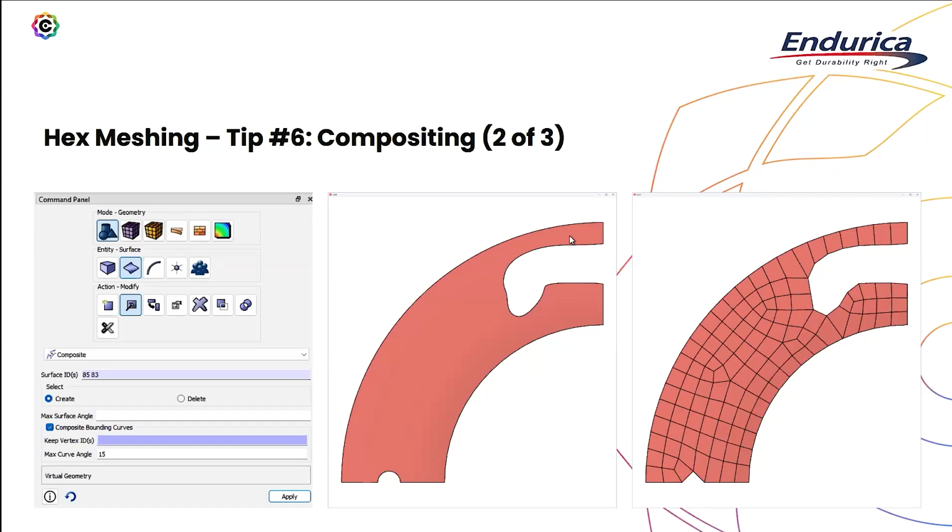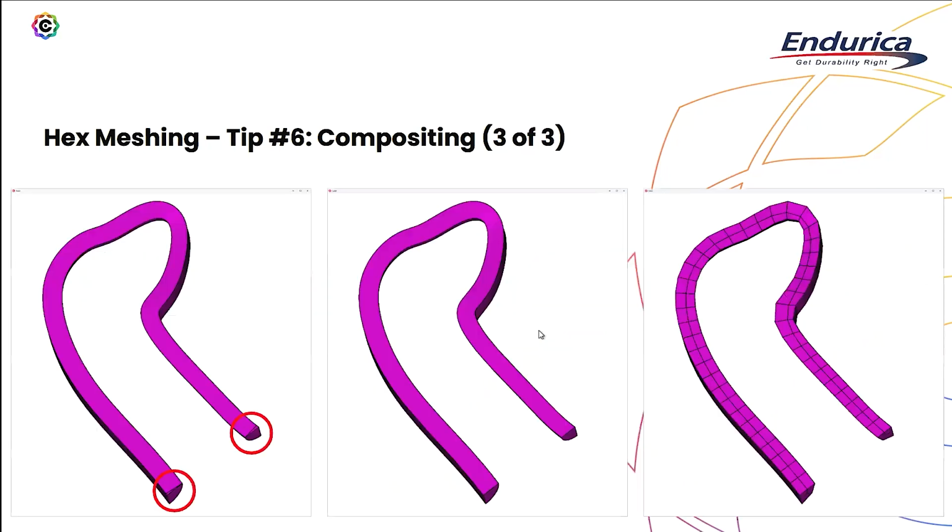And then finally, a third example. So that was just to get a better mesh quality. But in this case, the fillet was actually unmeshable just because of the way that we had to produce our web cut here. It resulted in these little triangle regions that would essentially force us to have a single layer of wedge elements and then go to hex elements and then come back on the backside to a final layer of wedges.